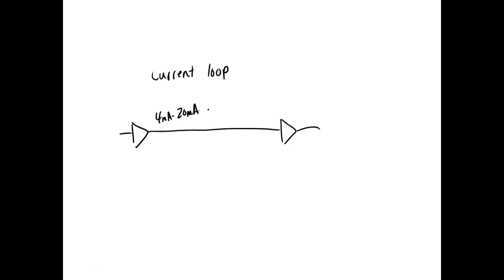is over here I'm going from 0 to 4 volts, and over here I'm getting 1 to 3 volts, right? It's still giving us the same resolution of so many counts, but over here 4 volts meant maximum output, and over here I'm only getting 3, right? So voltage can be really precise. It's just that we have problems maintaining voltage over distance. Now, of course, I is equal to V over R.